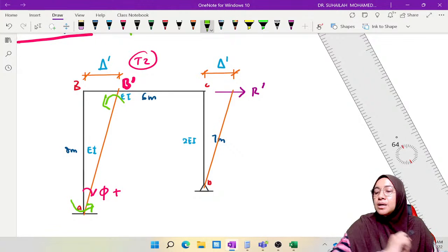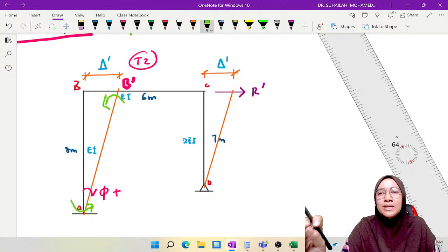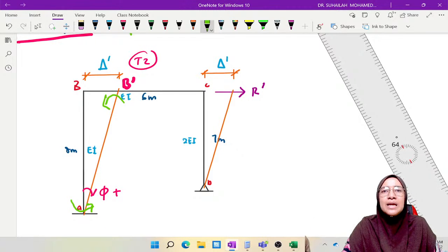So the one that we assume is not delta, the one that we assume is FEM. We suggest you assume a value of 100. The moment is 100, based on the suggestion by the textbook. But we have to check whether this 100 is negative 100 or positive 100, which depends on the behavior to counter back.